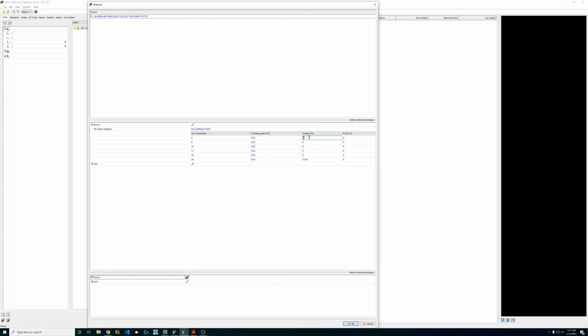And let's work now top to bottom on the chip load. So on 3 millimeter, it wants 22 micron per tooth, 600, tenth and a quarter. Yeah, sounds funny saying a tenth and a quarter, but this is metric, friends. 144. I actually misspoke. That's 166 and that's 187. Okay, what we have here is our cutter diameter, our cutting speed, and our chip load.